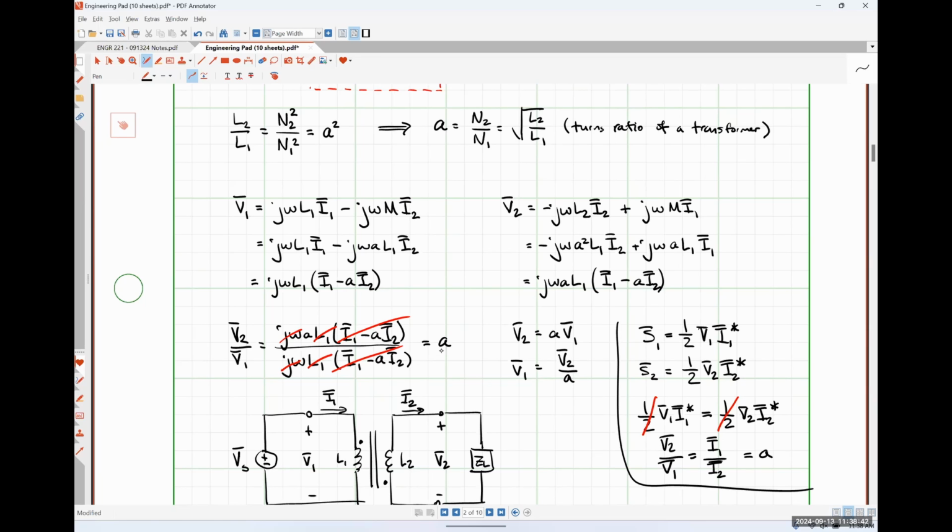So at an electric utility plant where they're generating power, they might only generate at something like 20 kV RMS, but they'll step it up to several hundred kV to transmit that power over very long distances, and then step it down one or two or even more times to bring it to the consumer so that we get just the 120 volts RMS that we're used to.